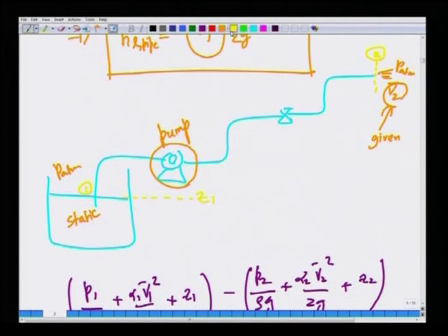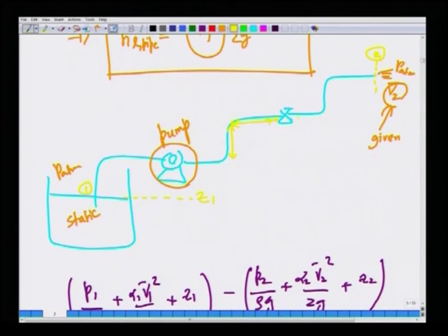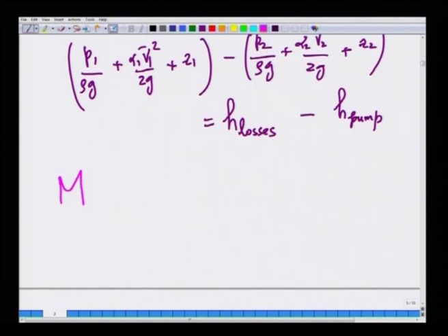Now, there are various segments in which the flow is through a straight pipe. Here we have to estimate the losses using the friction factor chart. So, whenever there are straight segments of pipes, the losses in those pieces of the pipeline network will have to be calculated from the friction factor chart. Such losses are traditionally called major losses, because they contribute numerically the most to the losses present.